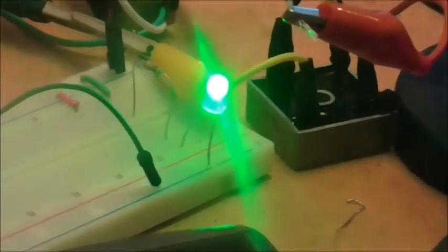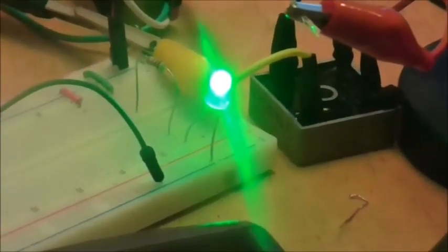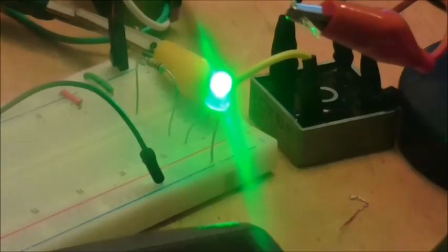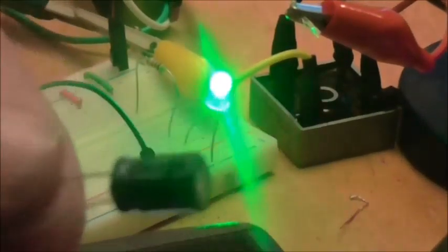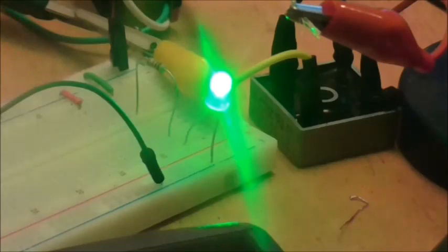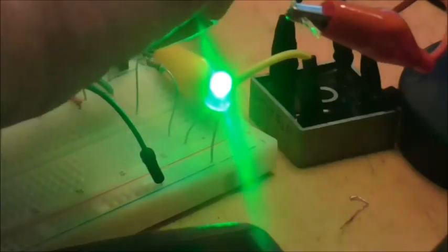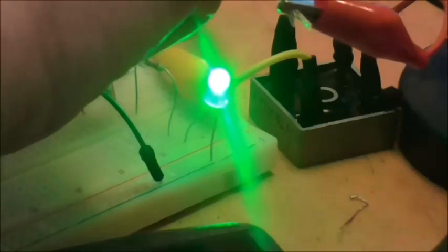is we're going to put a smoothing capacitor parallel to the supply, and this is an electrolytic capacitor, 470 microfarads, and it's able to deal with 16 volts. I would have liked to have used one that can deal with 25 volts just for safety's sake, but 16 volts is okay here, and I haven't got one at 25 volts, so let's just place him in there.